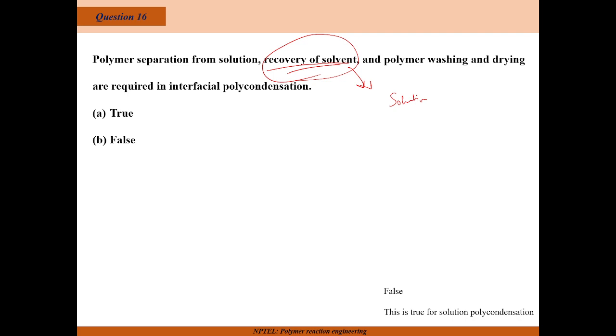And when we recover this solution, that will be a huge portion of this polymerization. We need not throw it away, because that will still contain a low molecular weight fraction in it. So that cannot be reused for the next step. So to remove that low molecular weight fraction, I have to go for a distillation where I will recover and reuse. So this is one part.